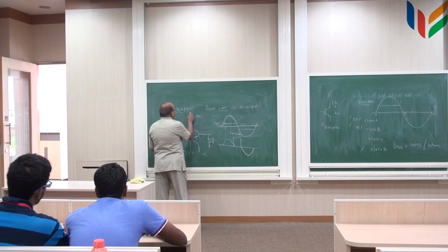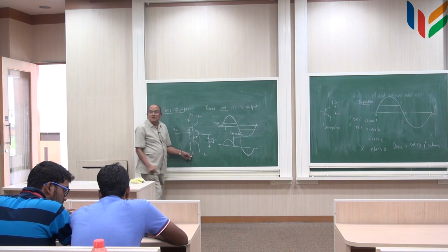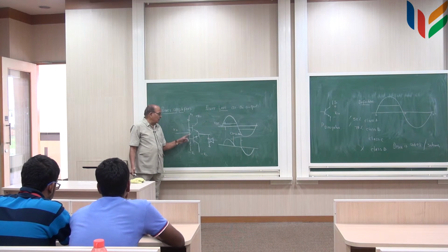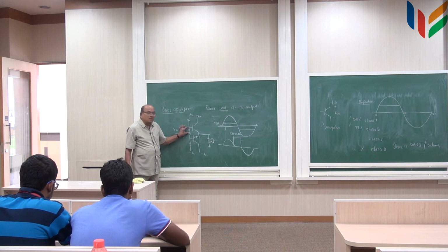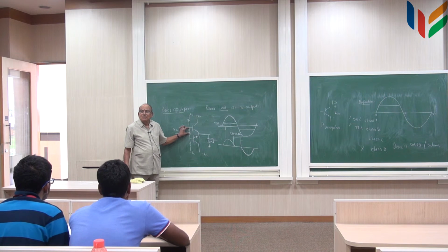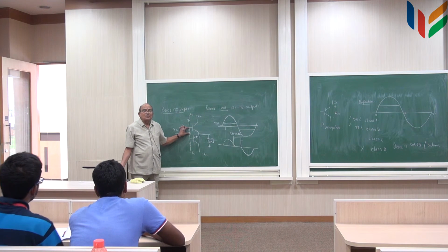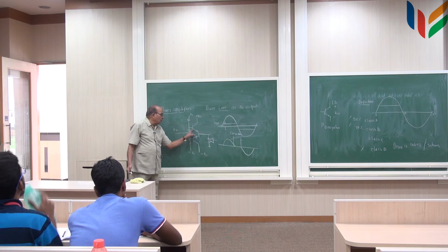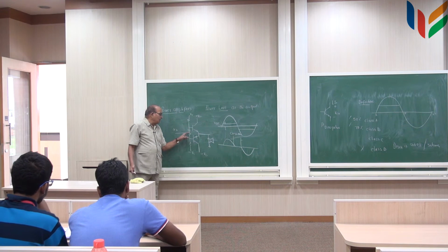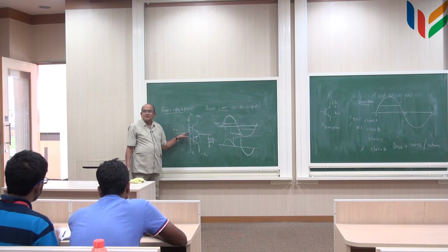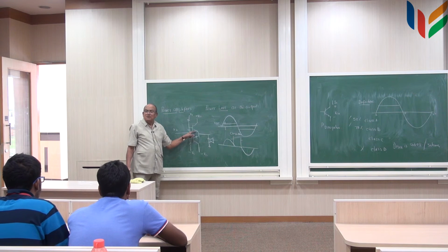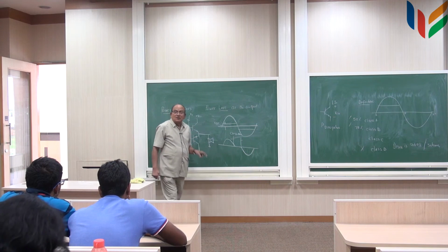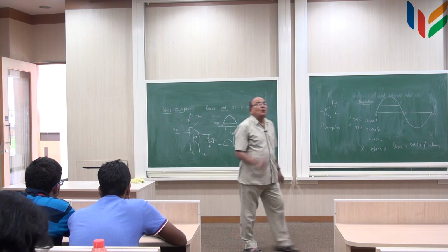This is plus VCC and this is minus VCC. And then what do I do? I put a resistor and put a diode on the resistor. The voltage across this is VBE, conducting diode, so the voltage across is VBE, and this voltage across is also VBE. So, now if you look at this loop here, this voltage here is same as this voltage. Right? This cancels with this voltage VBE. Similarly, this cancels with this VBE. So, now the two transistors are conducting for the full cycle.